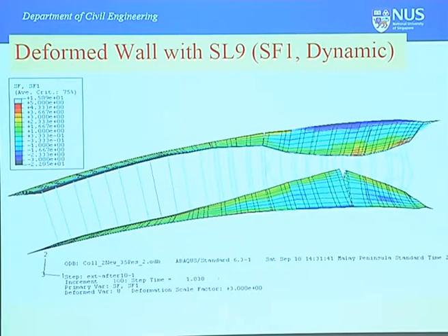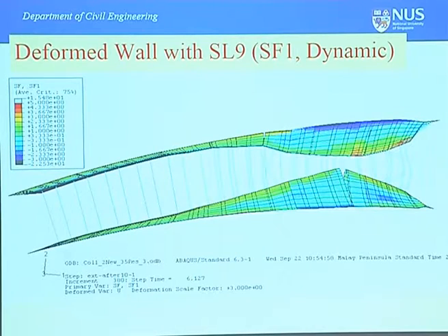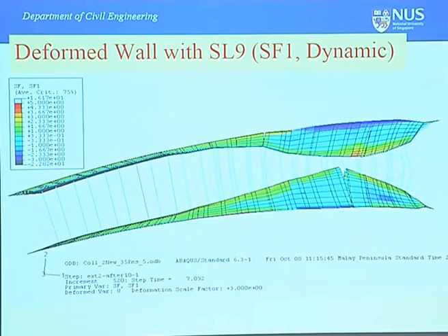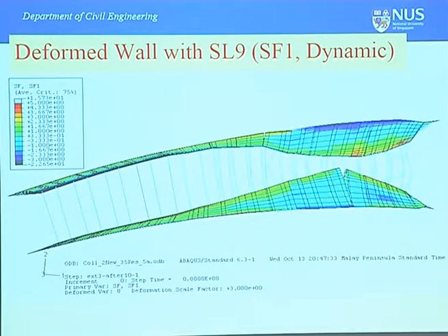This is classic progressive collapse. As a few sections of the strut buckle, they lose the load carrying capacity. The wall comes in, it loads the neighboring section. The neighboring section gets overloaded. They buckle, and then it transmits the thing forward. You know.